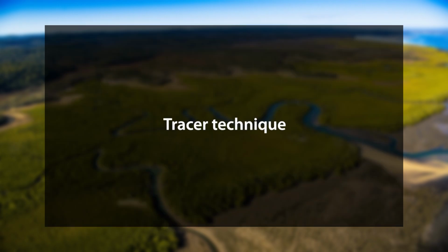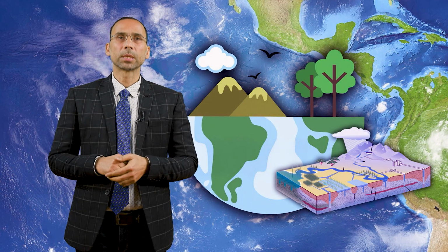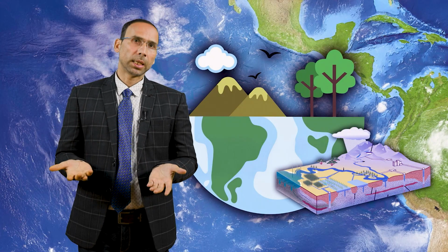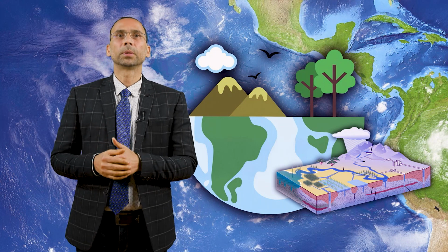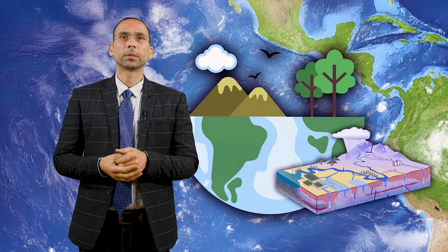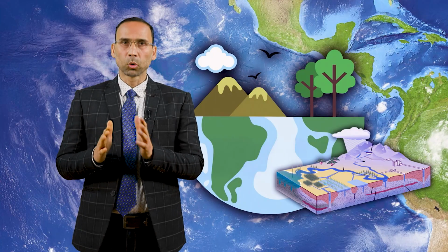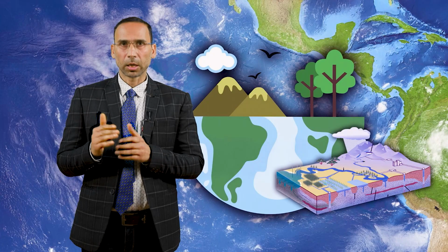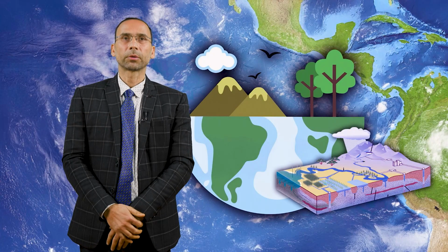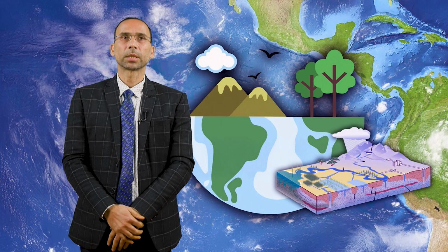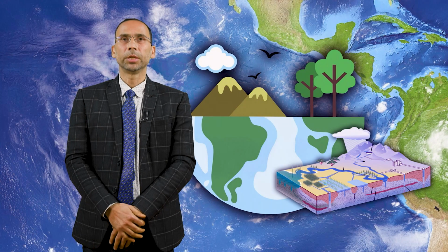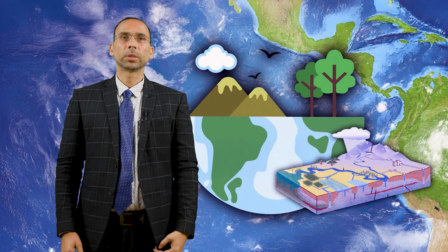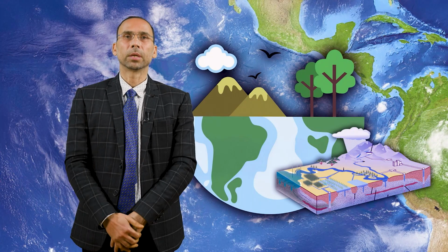Tracer technique. In this, a conservative substance is introduced in the hydrological systems. Tracer can be a natural chemical, isotope, artificial dye or even heat. The test investigates flow pathways, recharge processes, solute transport and aquifer connectivity. In karst aquifers, the tracer technique determines age, recharge timing and mixing processes. The technique has been used in several karst aquifers of India.